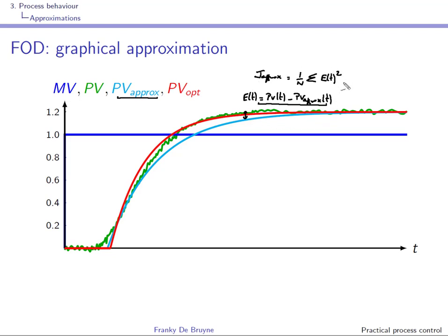And this leads to the idea that what you could do is try to minimize such a cost, okay? And this leads to an optimization problem where you minimize an identification cost that looks like that over Kp, t bar, theta bar, right?